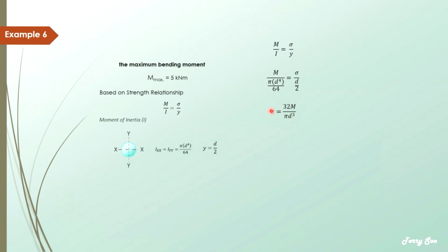Usually this is the formula that we use if we want to calculate the bending stress of a shaft. So the objective is the diameter of the shaft, so you have to change this to the subject. You have this, and then the whole thing cube root, you get a diameter of 0.0798 meter, which is also 79.8 millimeter. So you can round this up.